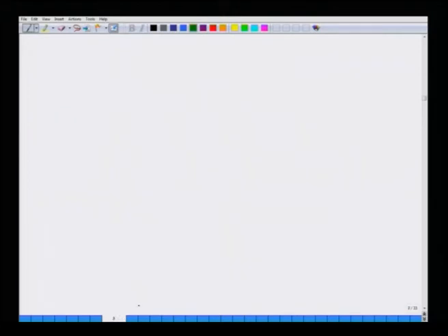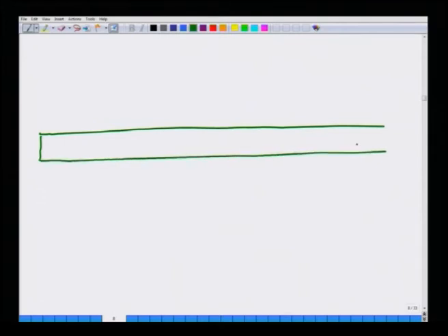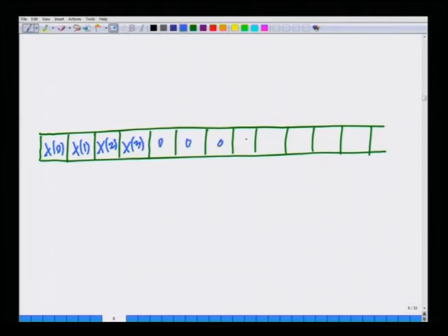Another simple way, as we all know, is of course to simply do a zero padding operation. So, I have again 12 subcarriers. What I can do here is load them onto the first 4 subcarriers and leave the rest of them 0. This is essentially zero padding based subcarrier mapping.